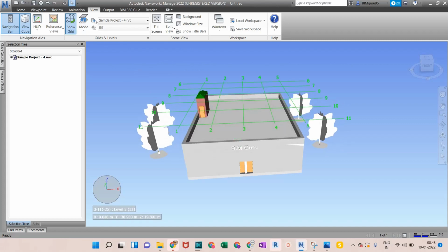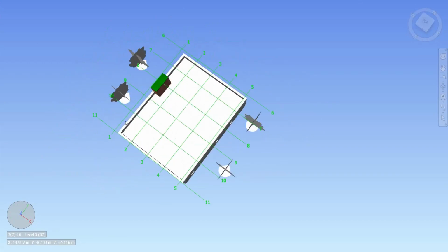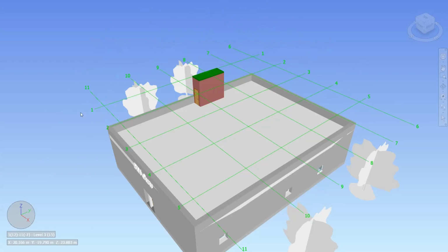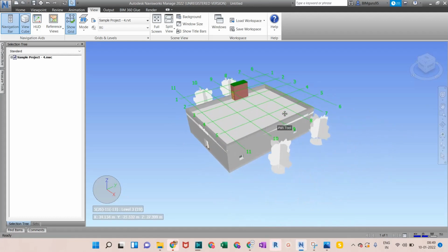Now if I move on to this icon, active grid right now of this particular project, because we have added this project right there. Okay, now if I move on to this full screen, if I click on that full screen, it will show me nothing but just my view, so that I can review thoroughly if I do not want to go anywhere else. But what happens when you're right there at the full screen? What do you need to do to go back in this situation? What you can do is press function key F11, so it'll be right back to your actual Navisworks view.